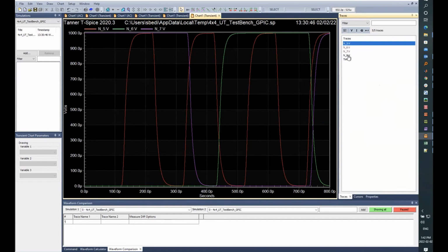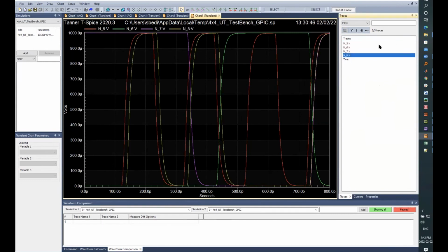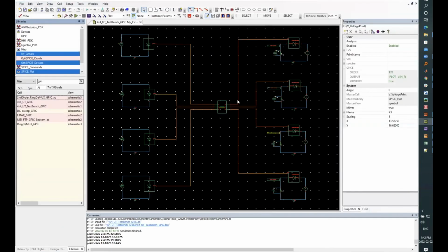So like I said, this way you can validate your mask layout schematic, and this shows how you can create your sub-circuit out of your mask layout: extract a netlist, create a mask layout, create a sub-circuit, and then feed it back into the SEdit tool, and you can run your simulation. So this basically concludes my presentation.